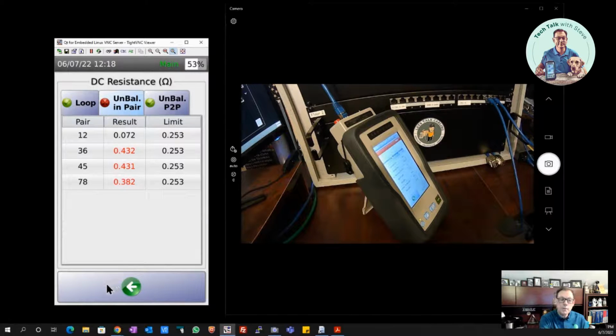So I know in this case, I may have some issues with the cabling. I may have to check the patch cords I'm using in my channel test to see if those are the issue, and then troubleshoot from there. So this cable using these patch cords would not support my PoE as I'd like it to. I probably could still run PoE over here, but I may have issues.